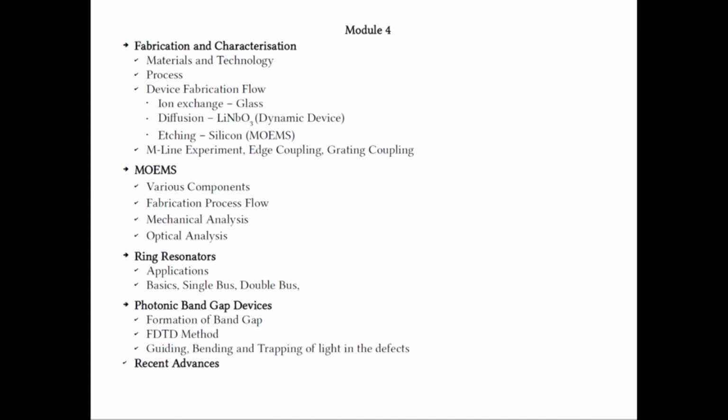In particular, they can be used for optical communication filters, and we have seen examples of a comb filter in this course, where you have rings of different radii, and then there is a common bus and there are bus waveguides to tap the output. We found that they provide a very sensitive function for different frequencies of operation. We have given some equations of their properties, like the Q factor, then the free spectral range, and so on and so forth.